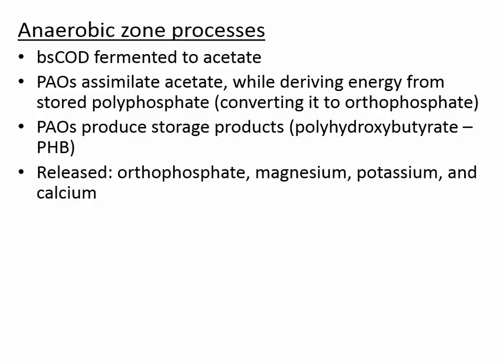So in the anaerobic zone, they're turning the polyphosphate, which we can settle, into something else. That's good. We want to settle out the phosphate. We don't want it dissolved. So they're doing this sort of dangerous, bad thing. They're converting it to orthophosphate, which means that actually inside the anaerobic zone, temporarily the phosphorus concentrations are increasing because they're shedding phosphorus. And in the process, they are producing these storage products. They have some energy that they're storing.